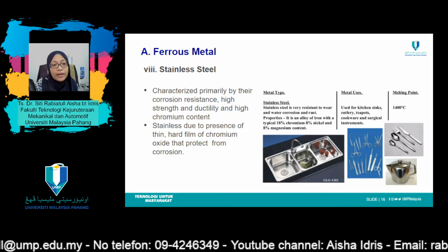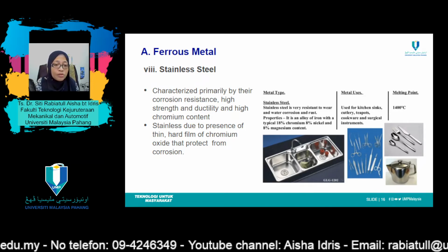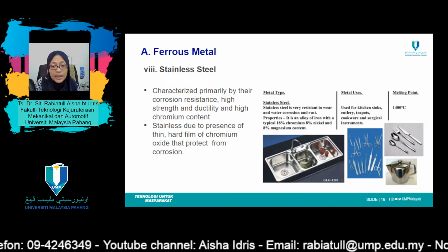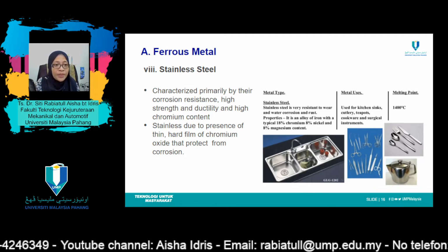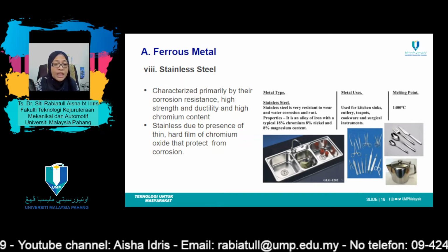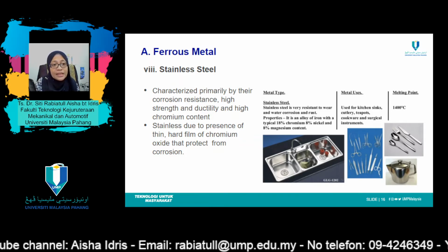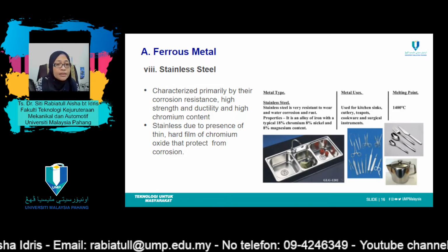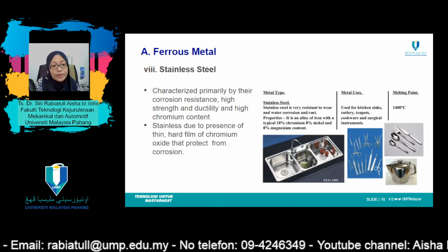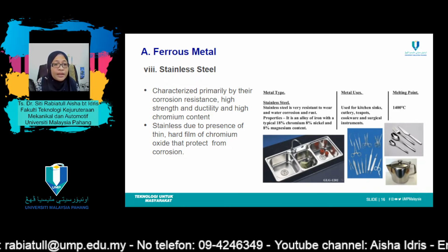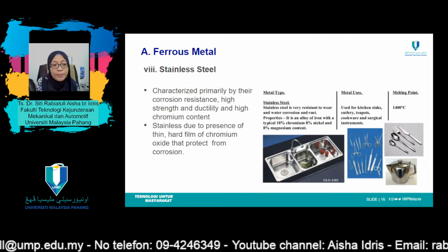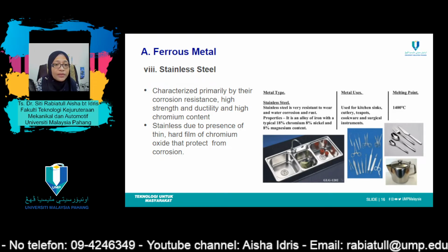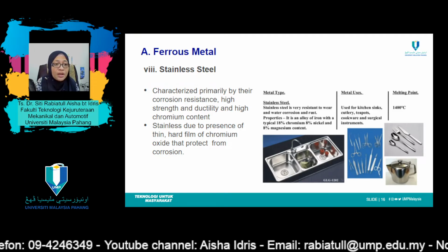Stainless steels are divided into three classes on the basis of the predominant phase constituent of the microstructure, which is martensite, ferrite, and austenite. Martensitic stainless steels are capable of being heat treated in such a way that martensite is the prime microconstituent. Additions of alloying elements in significant concentration produce dramatic alteration in the iron-carbon phase diagram. For austenitic stainless steels, the austenite phase field is extended to room temperature.